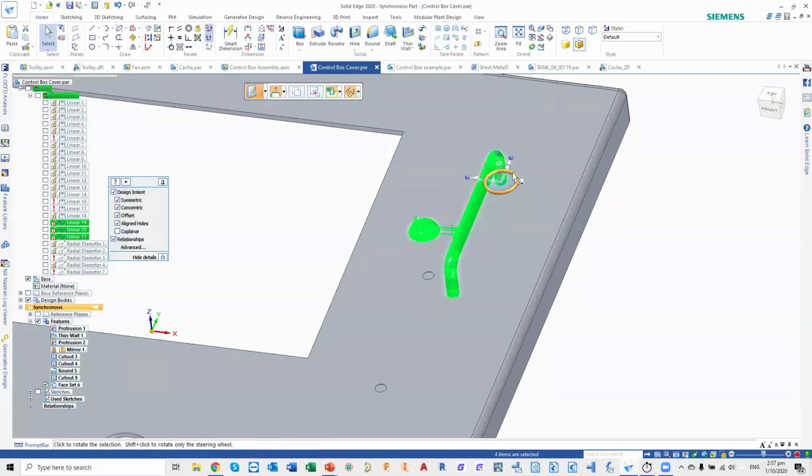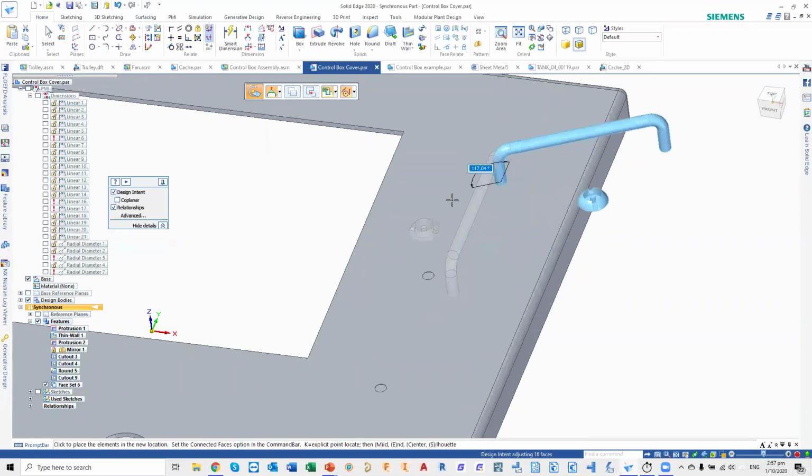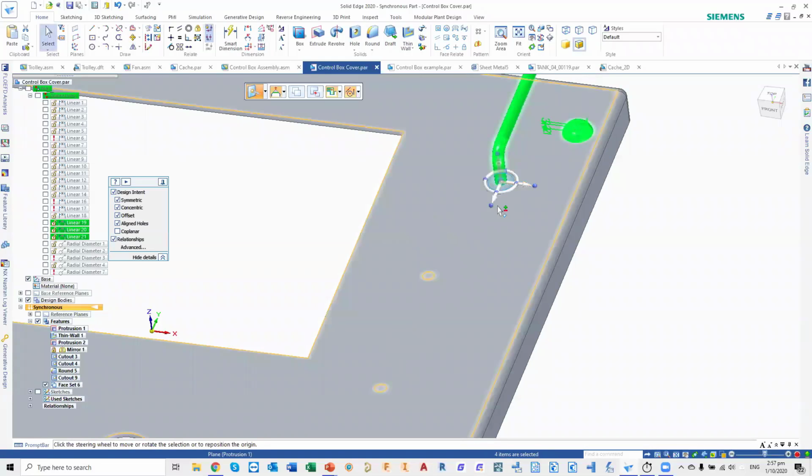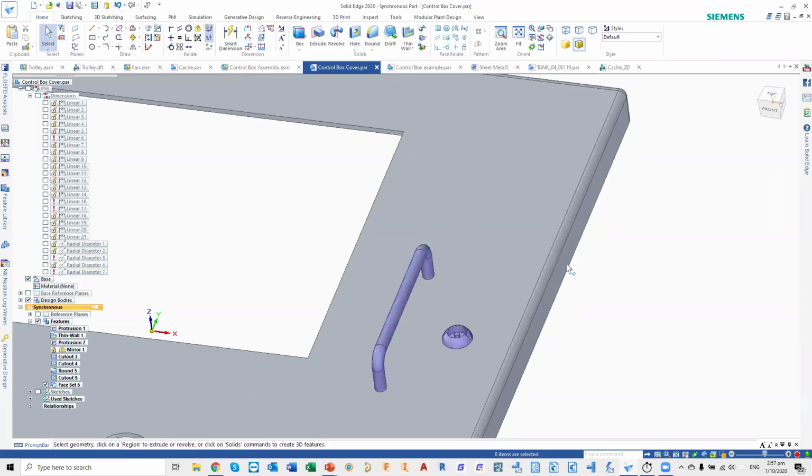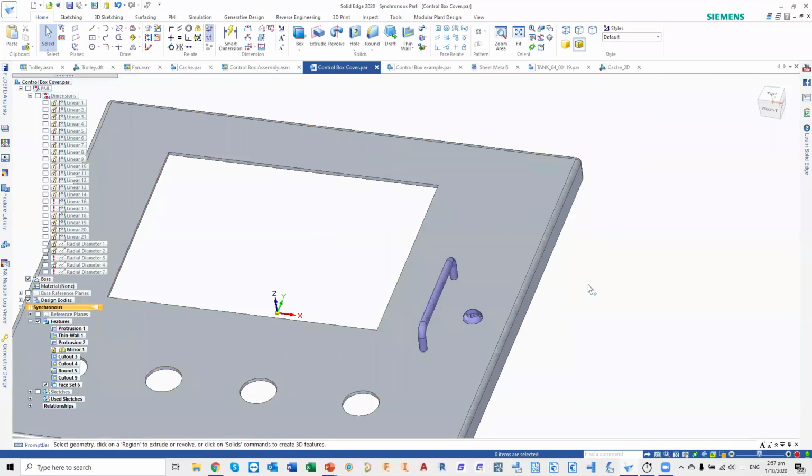Okay, after that, I'll make use of the wheel to reposition the feature that I've copied over. Now I've properly aligned the two features onto the correct position that I want on my casing in this model. But then you can see the color is different from my base model because we haven't attached the feature that we have copied from another model into this file. So the last step, we just need to attach it.